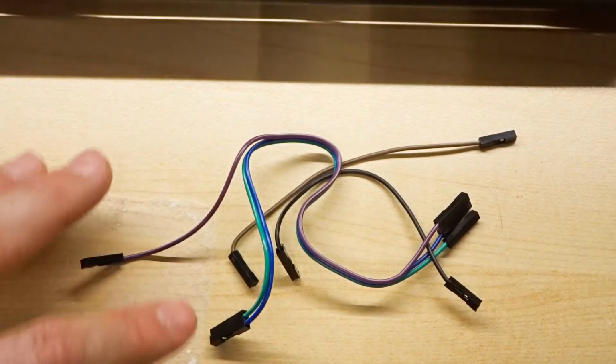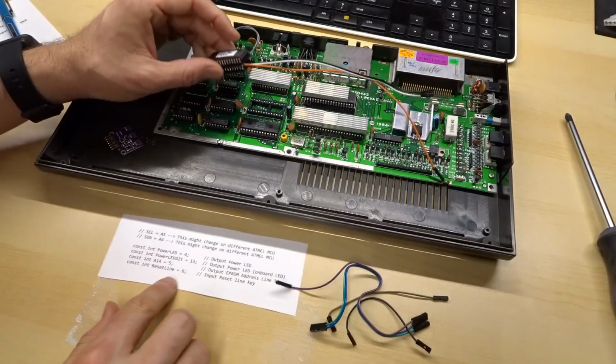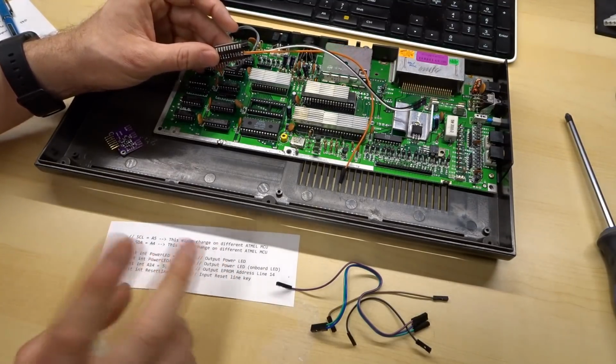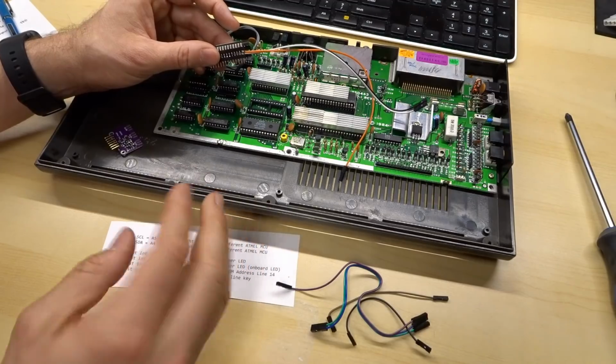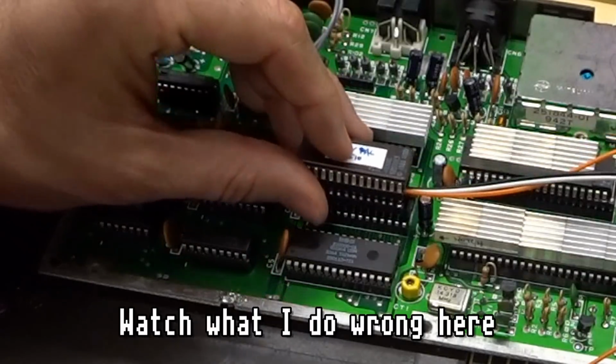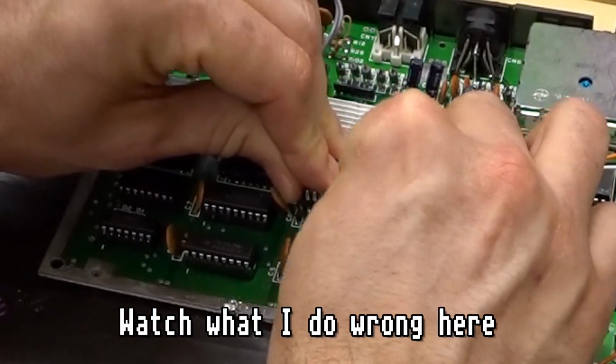And of course you're going to need a few interconnect lines. So some of these little Dupont jumper cables are perfect. It's very handy to print out a little piece of paper like this just to help you do all the connections. Double check, because you don't want to accidentally reverse polarity, plug the ground into the 5 volts. You could short out the computer doing that. So it's good to have a little handy printout. Let's put the EEPROM into the socket.